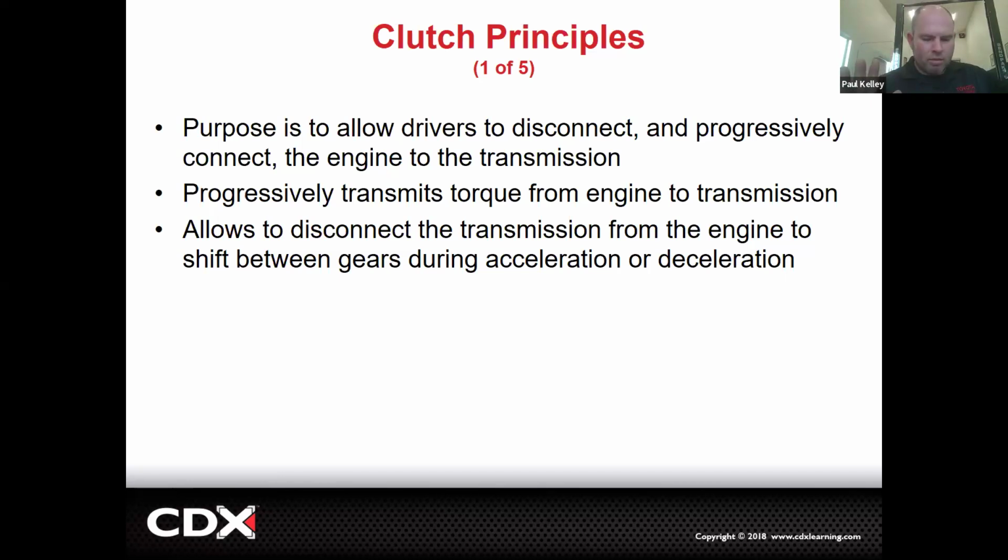Right. So considering that, when we think about the clutch, just remember the disc is squeezed by the pressure plate by default. Then all these additional components, the clutch master cylinder, the clutch slave cylinder, the clutch line, the clutch cable, whatever, all that stuff is there to release it. Now, let me clarify why I say that. If you were talking to the customer, you'd say, okay, when does this noise occur? Noises are pretty common in clutches. And they'd say, oh, when I engage the clutch. You need to be on the same page.